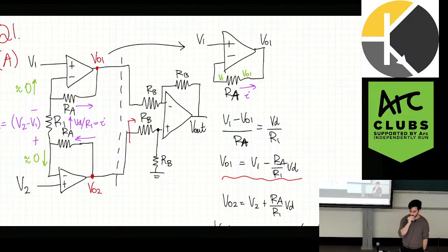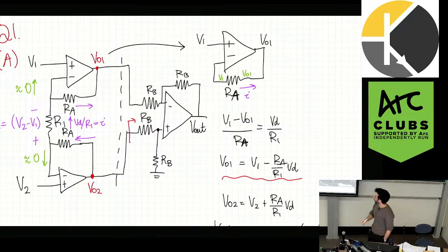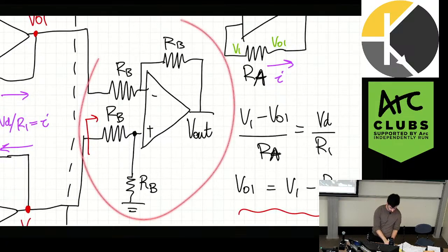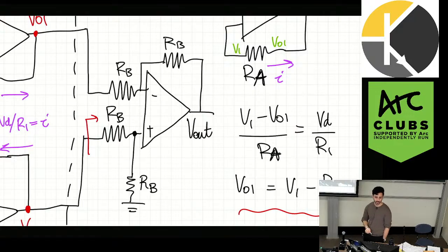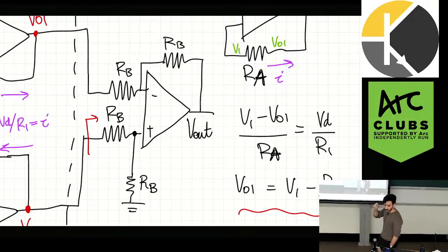Because you amplify the signal with two buffers, which have much higher CMRR. Yep. So essentially, if we were just doing the differential amplifier, the gain of 100 would have to be sitting here. We have to get the gain from somewhere, so we'd shift the gain to here. So if there's any shift in these resistors, all of a sudden there's a common mode gain, and that common mode signal is then multiplied by a factor of 100 through the gain, right? Whereas in this system,